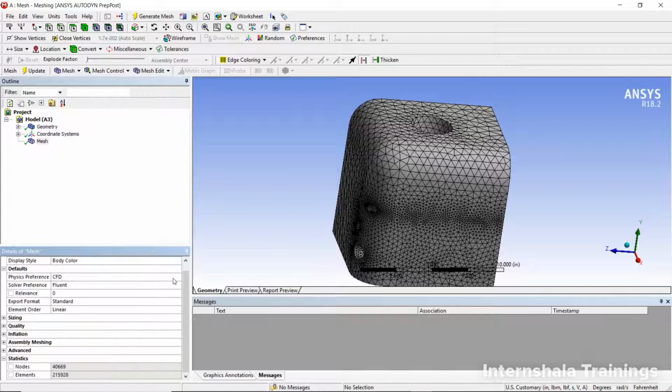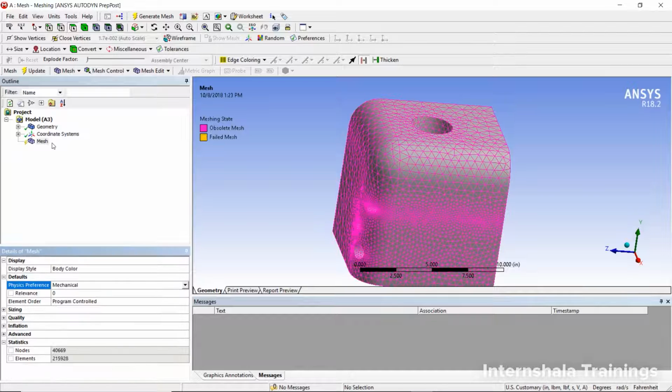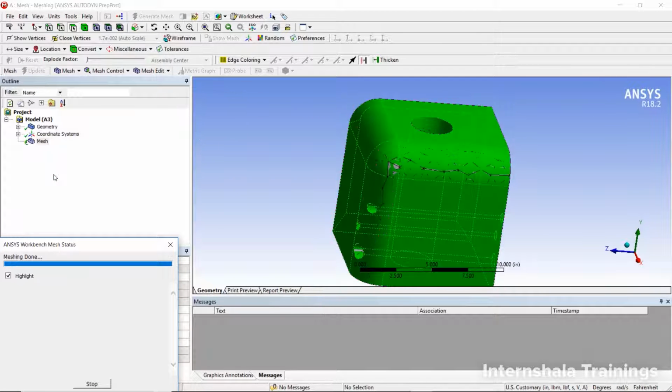Likewise, you can also select the type of solver. Generally, you have 2 to 3 different types of solvers inside Ansys Workbench for performing CFD. You have the Fluent solver, the CFX solver, and the Polyflow solver. So you can also select the settings from here as well. I'm going to go back to mechanical, and remesh this particular object by right clicking and saying generate mesh.